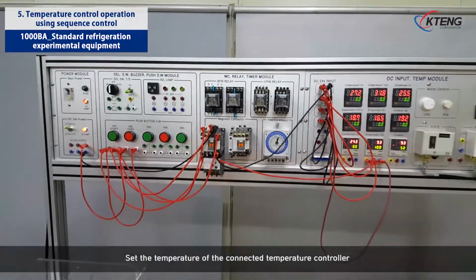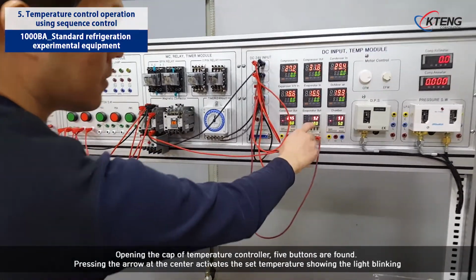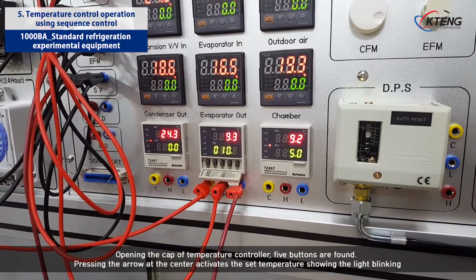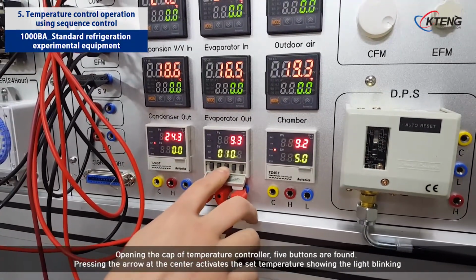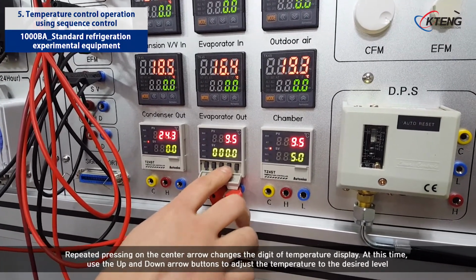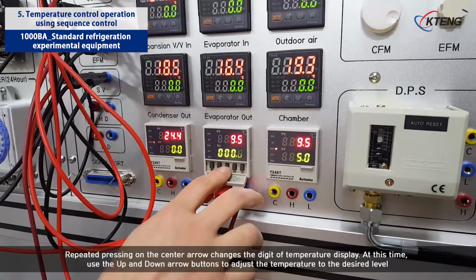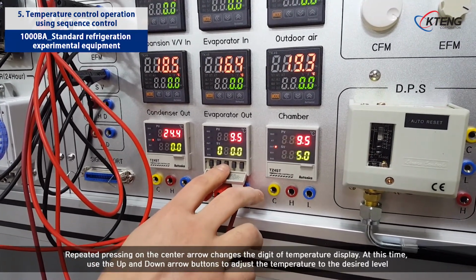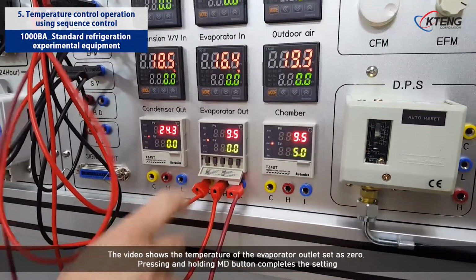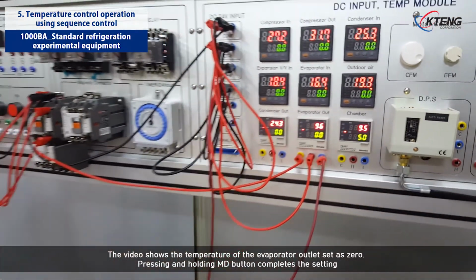Set the temperature of the connected temperature controller. Opening the cap of temperature controller, 5 buttons are found. Pressing the arrow at the center activates the set temperatures showing the light blinking. Repeated pressing on the center arrow changes the digit of temperature display. At this time, use the up and down arrow buttons to adjust the temperature to the desired level. The video shows the temperature of the evaporator outlet set as 0. Pressing and holding MD button completes the setting.